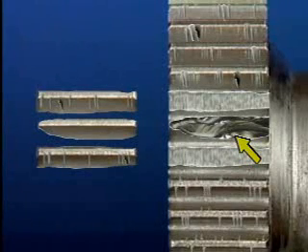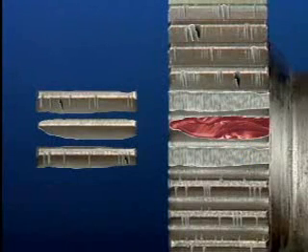Now, if the fatigue break area contains a large amount of reddish stain, as it does in this example, then that indicates that the break took a long time to develop and is further evidence of an internal defect. There isn't much that you can do about breaks caused by internal overloads other than replacing the damaged gears.